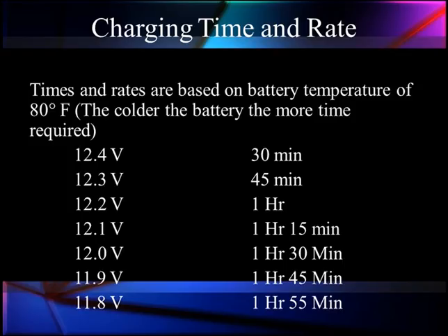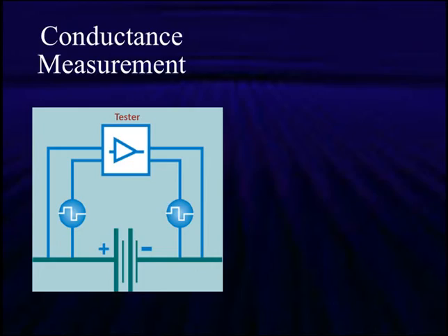If I'm at 12.4, it should take 30 minutes for the battery to fully charge. Look, if we're at 11.8, it's an hour and 55 minutes to recharge this battery. Don't expect it to accept a charge quickly if you're down in 12 volts or lower. Give it time to accept it. Let it make sure that it is going to fully recover. If you had a battery that wouldn't start a car because they left the lights on, odds are you're in this 12 volt range, and a 15 or 20 minute charge is not enough to turn it loose. You have to pay attention to this.